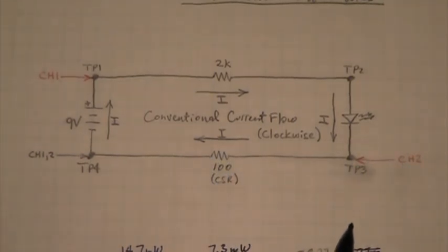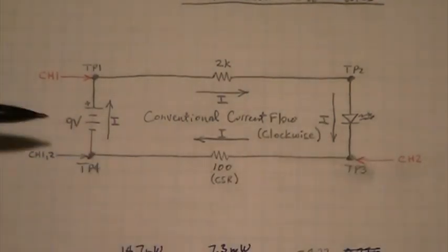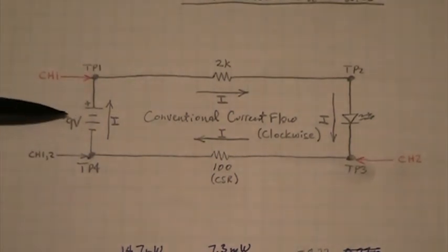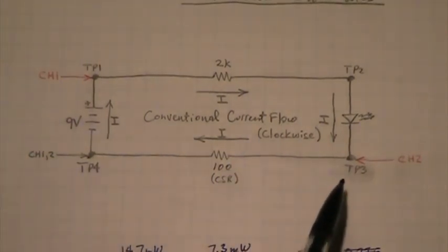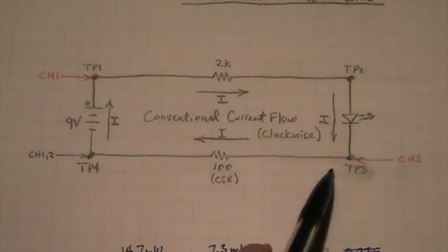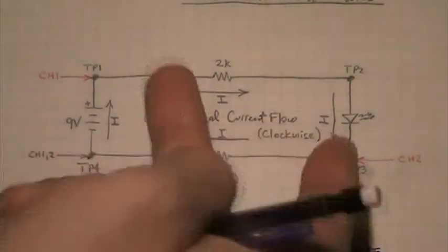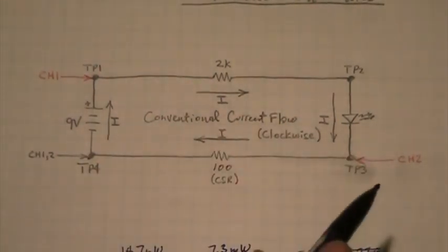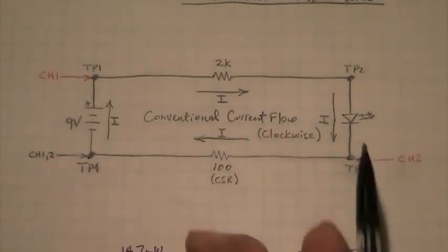Now the easy solution to this, in order to retain the proper phase of our power measurement when we finally get the oscilloscope to compute the average power of the battery, is to simply use the invert function on the oscilloscope to invert the polarity of the channel 2 probe. So it effectively is like switching the probes around so that our positive is here and our negative is here.